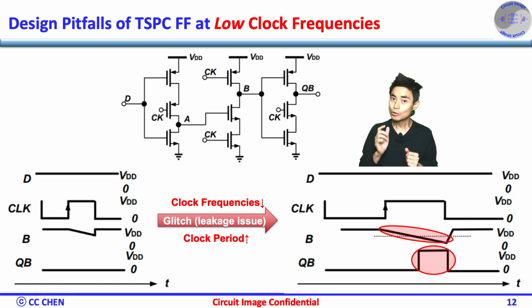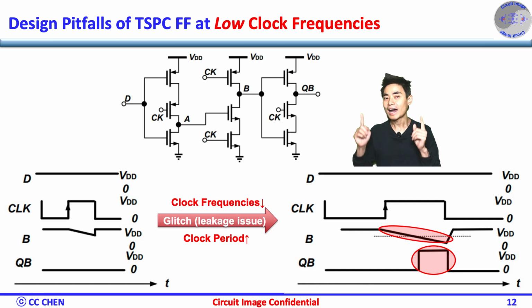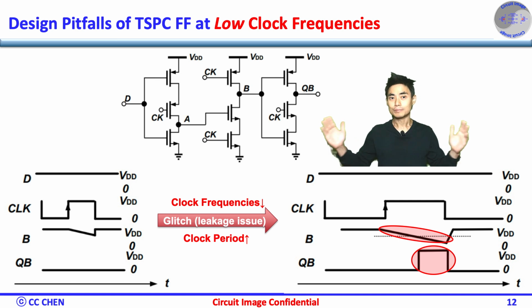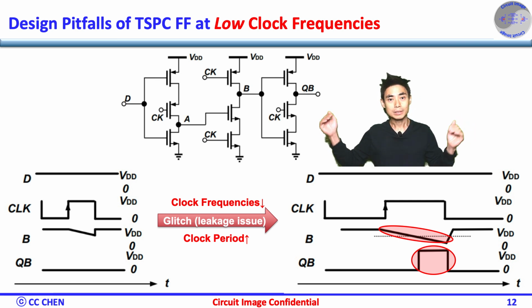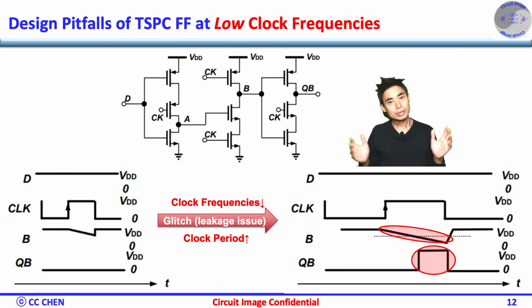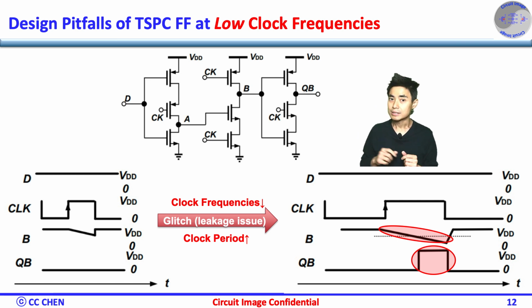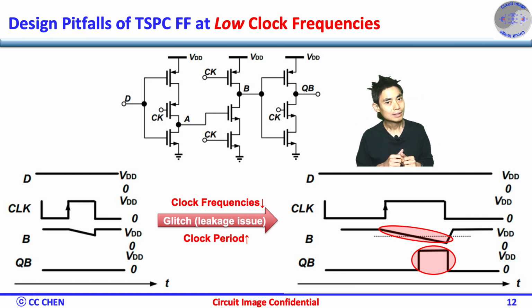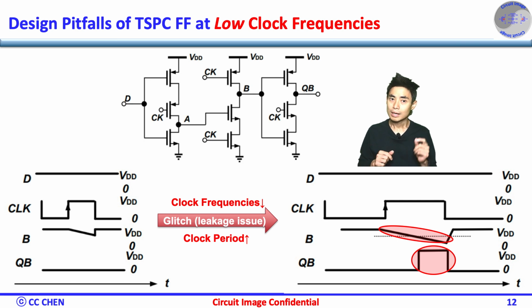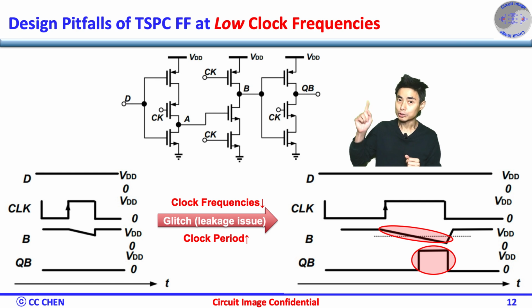at sufficiently low clock frequency because of the comparably high leakage. For example, if the clock period is very long, the whole charge would be lost through the transistor leakage path from its substrate conduction. Then, the source and drain junction corrupts the stored state. The leakage issue is serious in the fast corner, high temperature, and high supply voltages.